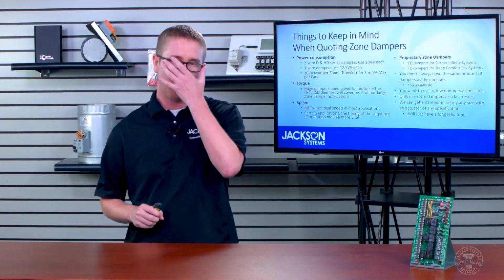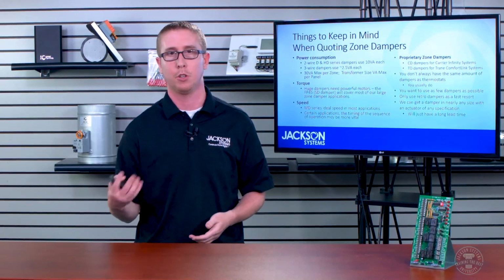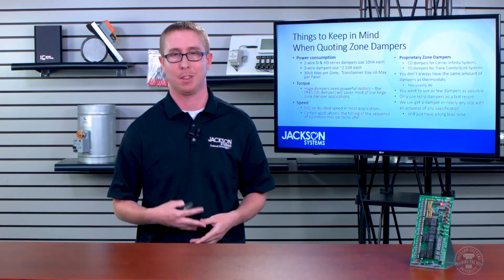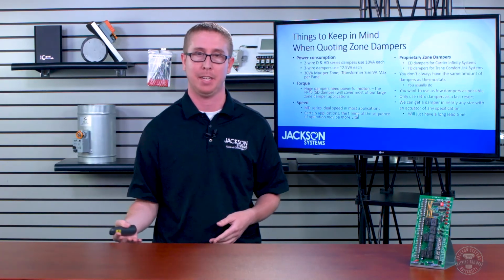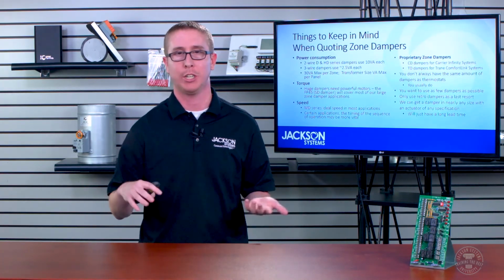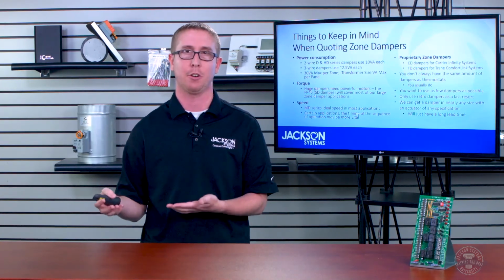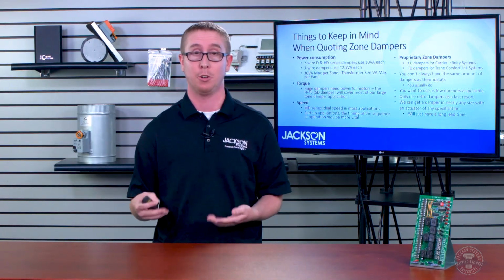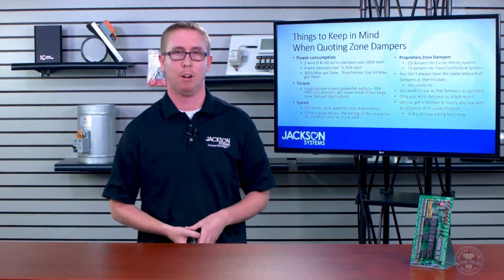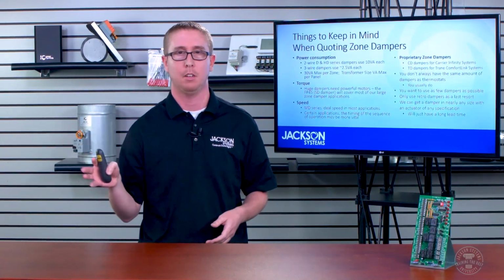Things to keep in mind when quoting dampers. The first thing is power consumption. So again, the 2-wire dampers are consuming 10 VA apiece compared to 3-wire dampers, 2.5 VA apiece. You can kind of tell just off of that. Once you get to 3 or 4 dampers, you really still have to consider the power consumption on a 2-wire damper. On a 3-wire damper, you're talking right around 20 dampers or so before that's even really a thought.